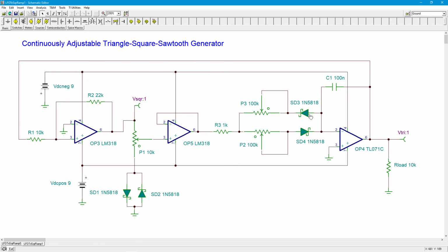We have to have them here in order to sort of direct the path of current flow. But here we have them just to sort of compensate for the unideal effect. If somebody ever invents a diode that has like a 1 millivolt turn on, oh man, life would be great. But I ain't holding my breath for that. In any case, we just adjust this pot, which adjusts this voltage, which in turn adjusts the current.